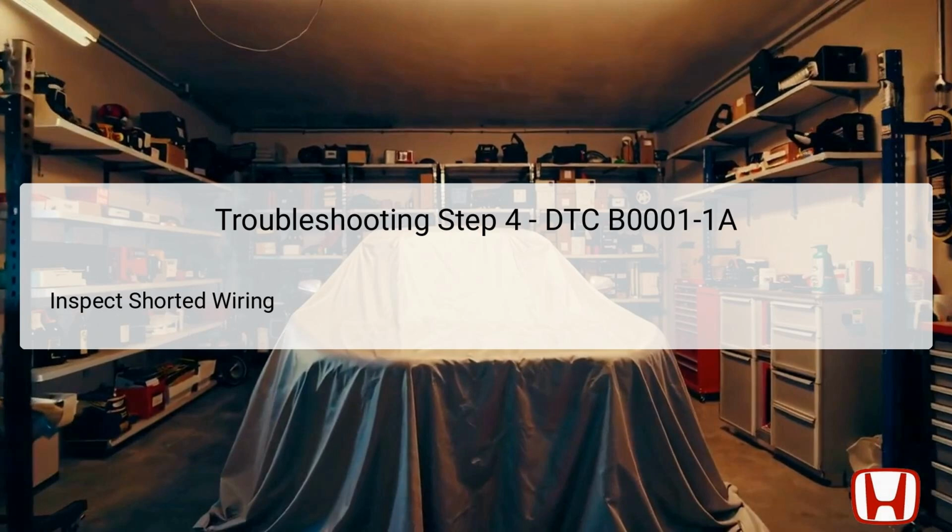Test the wiring from the SRS unit connector and inspect the LA1 plus and LA1 minus connections for any continuity issues. Normal conditions dictate that the resistance should exceed 1 megaohm, indicating no shorts. In case of abnormal findings, it may suggest a more extensive issue within the SRS wiring, requiring further investigation and potential repairs to safeguard the vehicle safety systems.